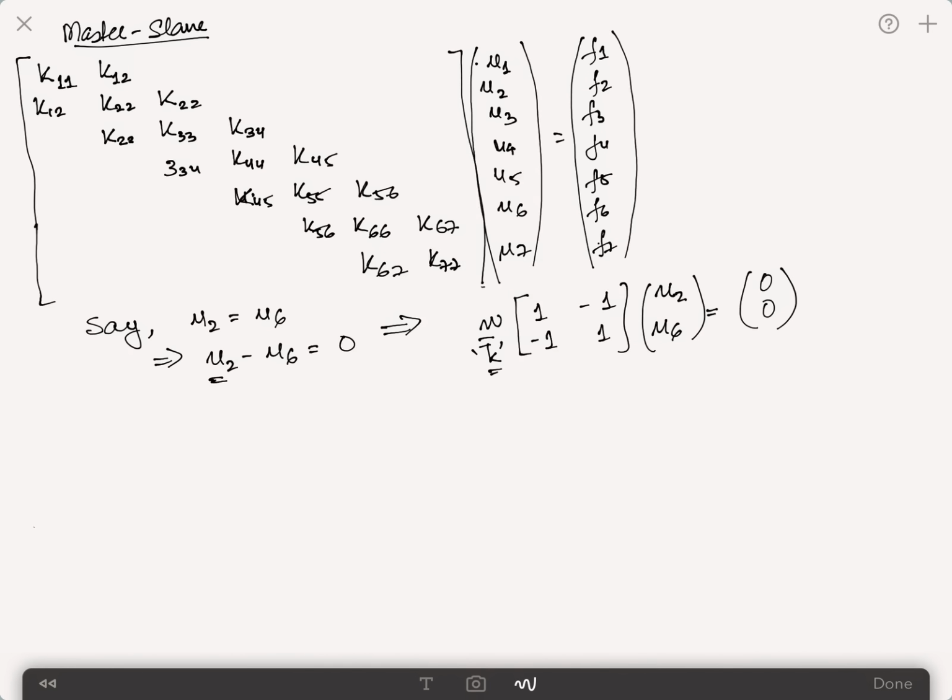So how this is going to change is that it's going to add certain elements into the stiffness matrix. So we will add penalty elements, and when I said element, I actually meant an element to the stiffness matrix. So instead of writing the whole stiffness matrix, I'm just going to add the penalty terms into the existing stiffness matrix.